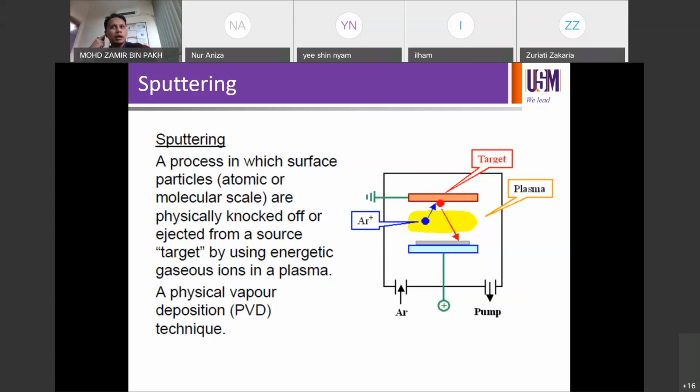Jenny, can you still recall last time what your base pressure was during sputtering before you start the plasma? You need to pump down before you start plasma. What's the range of the pressure for the base pressure?